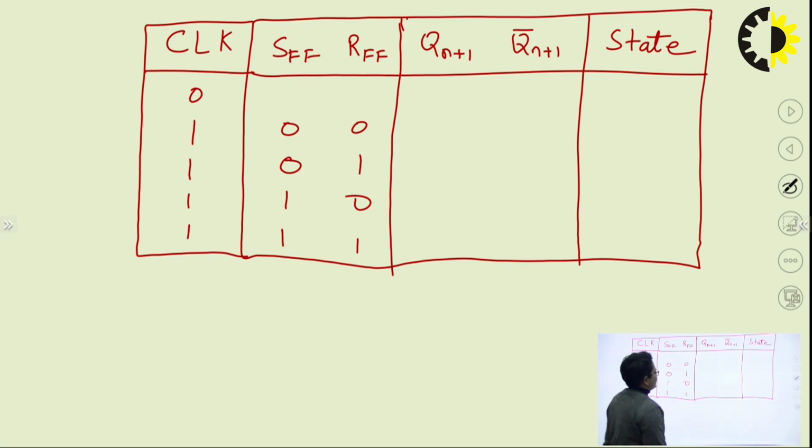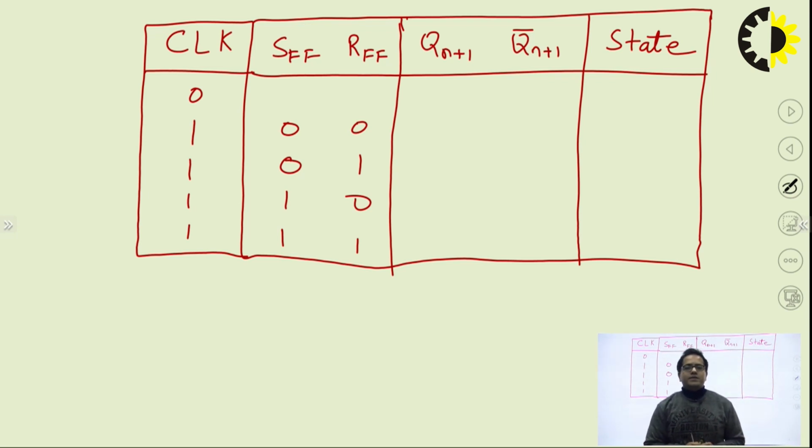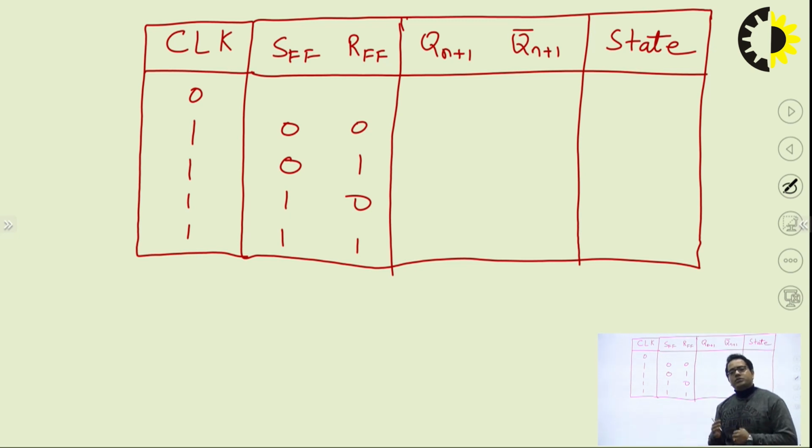Now, in the last class, we discussed that whenever the clock is not provided to the input of the SR latch using NOR gate, irrespective of the values of the input terminals, your flip-flop is not responding; it is holding its past value. Similarly, in this case also we are going to discuss that if we are not applying a clock pulse, how it is going to respond, and whether the concept that we have built is still valid at this point or not. We have drawn the circuitry in such a manner that whenever we are not applying a clock pulse, your circuitry should hold its past value. That means it will remain in its hold state, holding its past output.